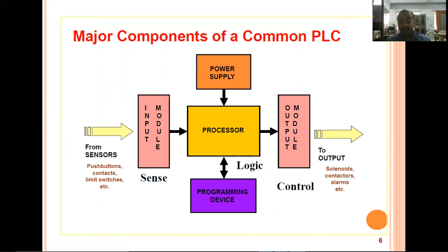But not only that. As the name suggests, it's a programmable logic controller, so the logic needs to be given by the user through a programming device. So the programming device will also be there. Using this programming device, we can give the information to the PLC. Mostly in India, we use ladder logic to give the logic to the processor, and the processor can understand which type of logic we are trying to implement, and according to our logic it acts.